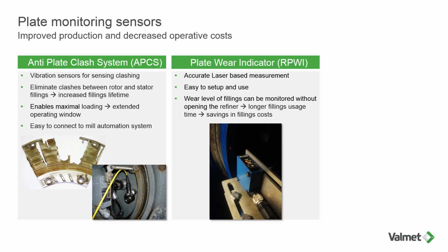to monitor plate life. It's also going to be a good way of indicating when it's time to change your plates. You don't want to change your plates too early if there's still bar edges left and they're still usable. You would be wasting time and money in replacing the plates. You don't want to change them when it's too late, because the same reason, you're going to have a catastrophic failure, or your refiner is just going to quit on you. There's no bar edges to do any work. There's no bar edges to do any pumping, and you're not going to get any pulp to your next chest. If you do, it's going to be unrefined.